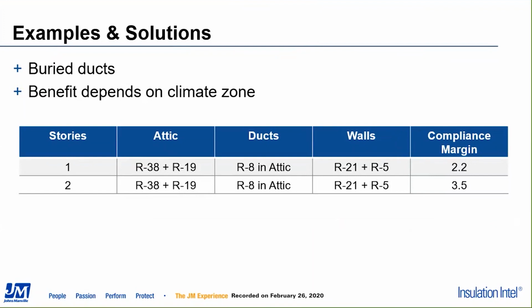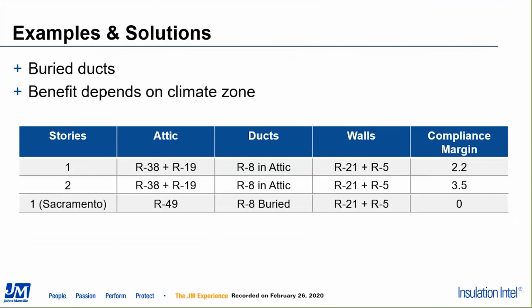So next, buried ductwork, right? We talked about that a little bit. And so again, we're going to start off real quick, right? Those first two attic designs, and whether or not buried ducts works really depends on your climate zone. So if we were to do, let's say, some deeper attic insulation, R49, and if we did some measures to let us claim that that R8 ductwork is buried, and we're still in Sacramento, notice we lose a little bit of margin, but we're at 0. So we are still in compliance with that sort of an approach.